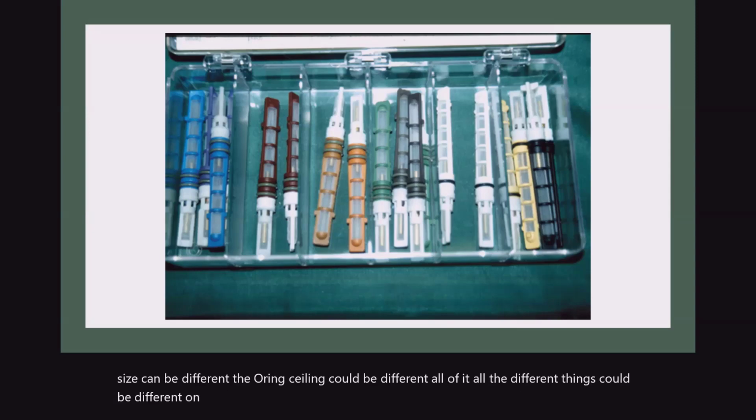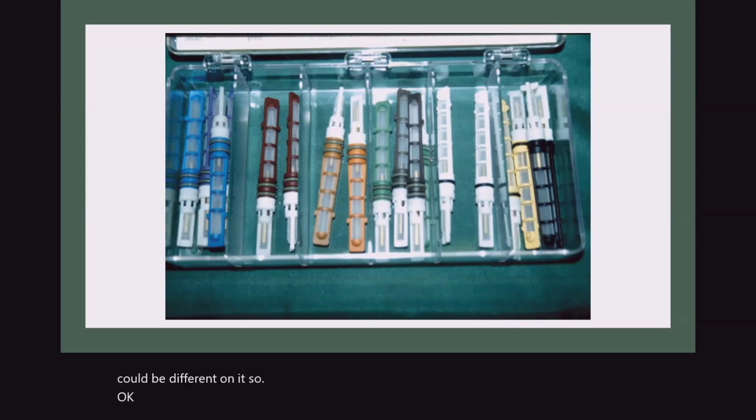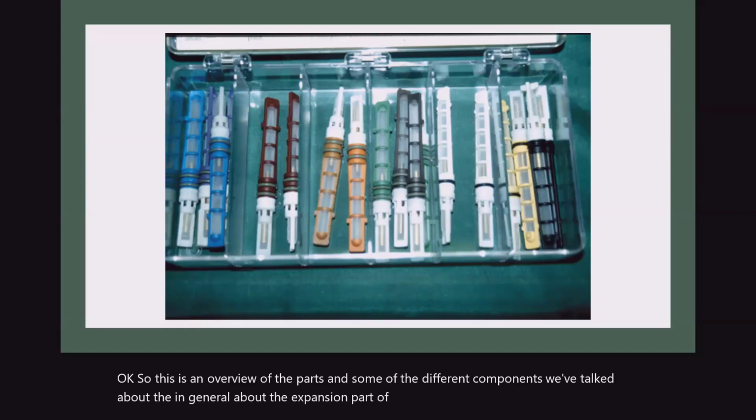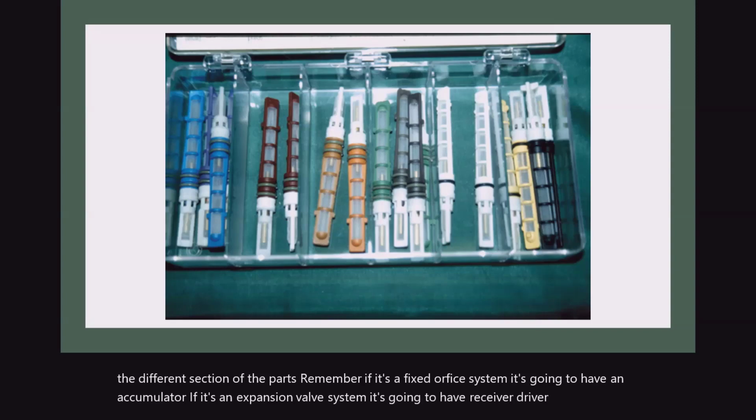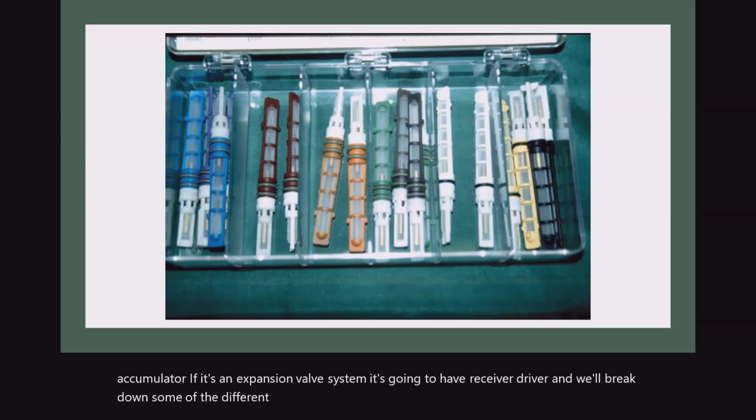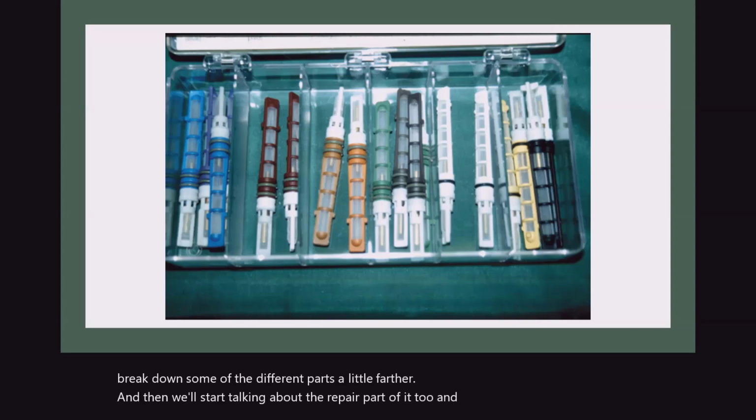So, okay, this is an overview of the parts and some of the different components. We've talked in general about the expansion part of it. We haven't really talked too much about the different sections of the parts. Remember, if it's a fixed orifice system, it's going to have an accumulator. If it's an expansion valve system, it's going to have a receiver drier. We'll break down some of the different parts a little bit further, and then we'll start talking about the repairing part of it too, and diagnosing it. Don't forget that part.